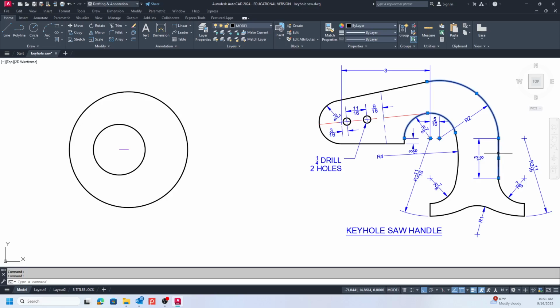Next thing we are going to do is put this 1 3/8 line. That line is straight from quadrant straight down at 1 3/8 of an inch. Draw a line, 3 o'clock quadrant, straight down. Input 1 minus 3/8 in CAD. Hit enter once, twice to accept that. Double check that, make sure it is 1 3/8.